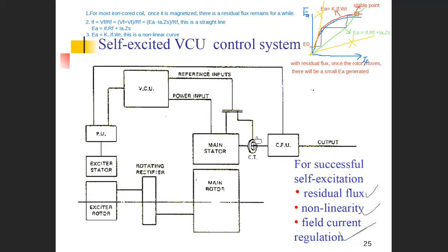And also at the output terminals, we have the current monitor system. That is the current CT, because the generator output current will be very big. It monitors the loading current levels. Meanwhile, we have one of the sensors monitor the terminal output voltage. So we have the terminal voltage monitored here, and the armature current monitored here. So, monitor the terminal voltage, monitor the terminal currents.